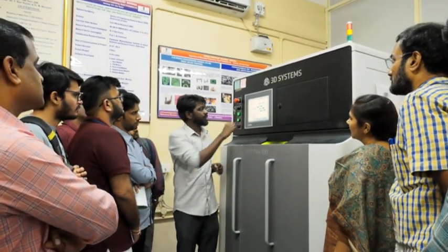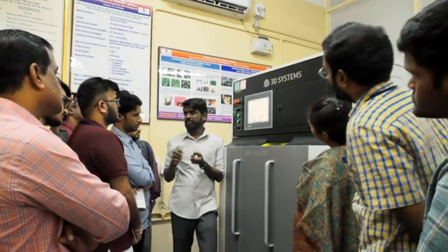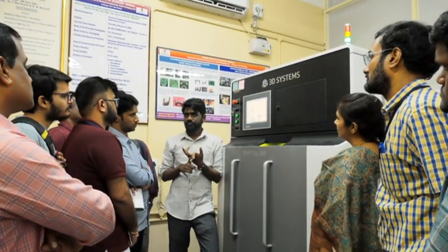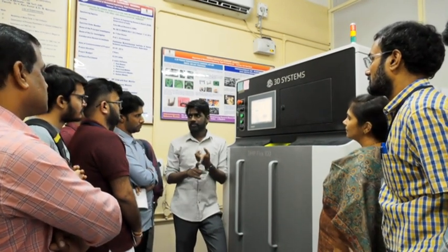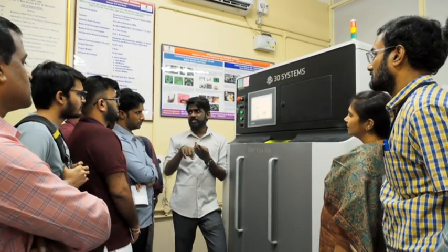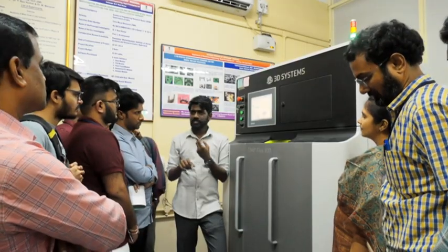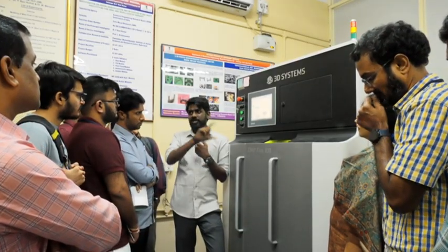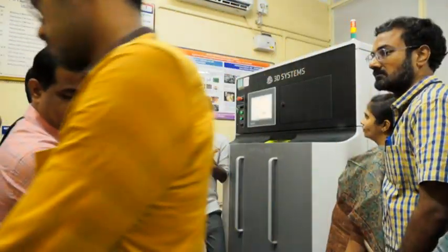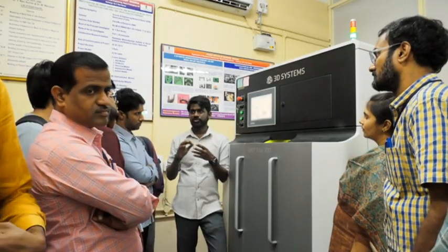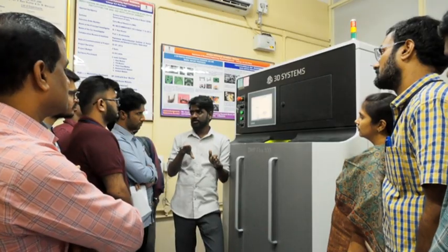And it will show you the estimated powder height. It depends upon the different powder particles. How do you calculate it? Same concept, density equals mass by volume, right? You have to calculate the mass by multiplying with density. Different materials mean different density: titanium has a different density, steel has a different density. Volume will be 100 into 100 into the height. Based on the calculations, you get this much height, so this much quantity is required. You have to load the powder like that.